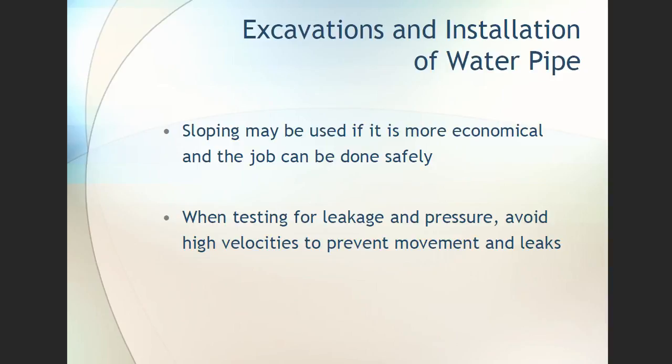Sloping may be used if it's more economical and the job can be done safely. When testing for leakage and pressure, avoid high velocities to prevent movement and leaks. One of the things you always want to do when you're installing a water pipe is get it to the point that it's pressurized before you backfill it, before you cover it all with dirt. It's a lot. You don't want to go back and have to start digging it up. Believe me, it's a lot of work.